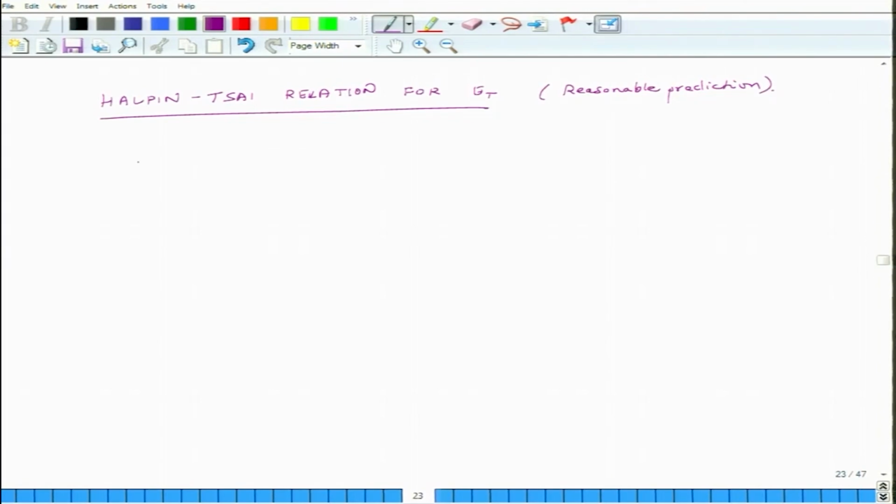What does this say? That if you want to compute ET, you can compute it using this relation. ET over EM equals 1 plus zeta eta Vf divided by this term, and this is a parameter. So, eta is a parameter and it can be computed by using this relation.